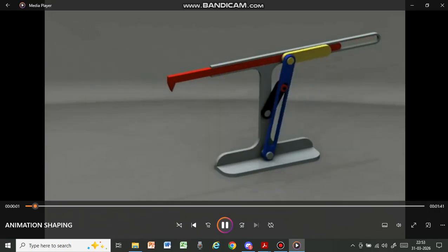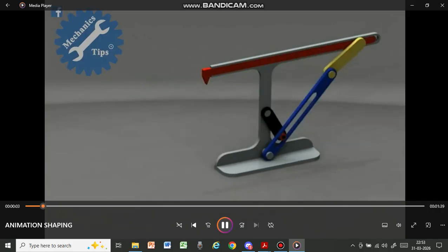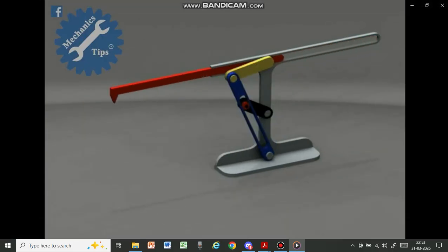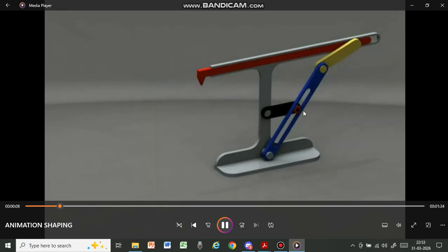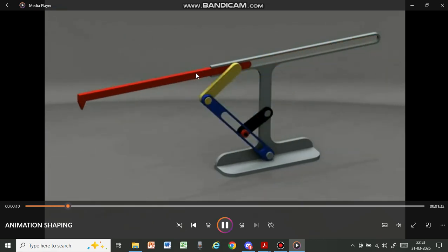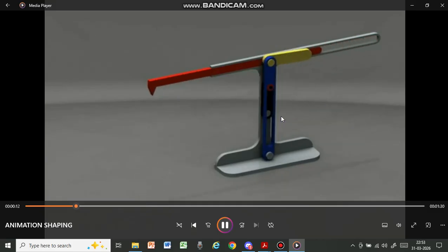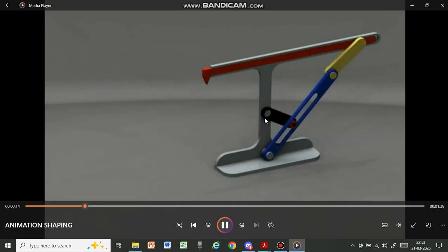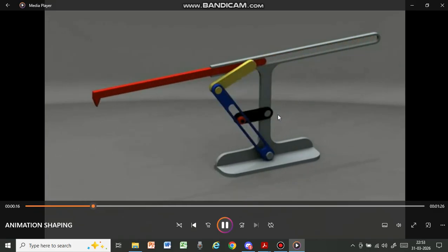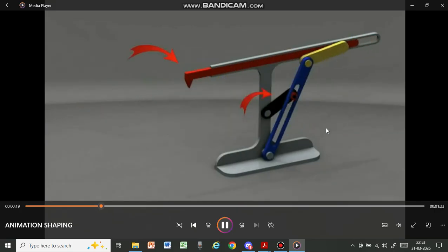A quick return mechanism is used where there is a need to convert rotary motion into reciprocating motion. Many machines have this type of mechanism, in which the forward stroke and the return stroke are not equal, and the return stroke is faster. The best workshop example is the shaping machine. This mechanism is made of a driving crank and a driven crank. The slider mounted on the driving crank is rotated from the bull gear.